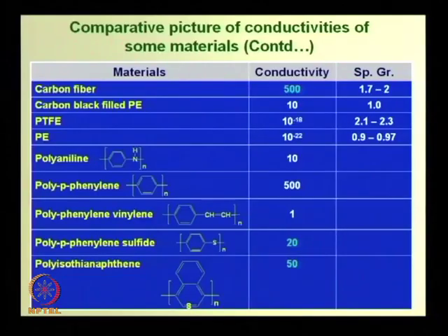So, carbon fiber, and you see in my lab there is carbon fiber. You can see that carbon fiber is made from a precursor polymer. What is that precursor polymer? PAN, polyacrylonitrile, that is converted to carbon fiber. People have made carbon fiber from phenolic resins also. I have seen report that people have made carbon fiber from natural fibers, from phenolic resins.